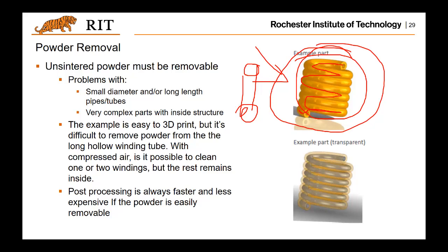He should have designed some holes or open features for the liquid resin to come out, but he didn't realize it, and it turns out all the liquid resin was trapped in the part, and of course the part cannot be used.